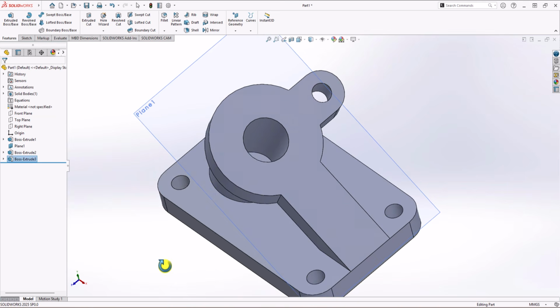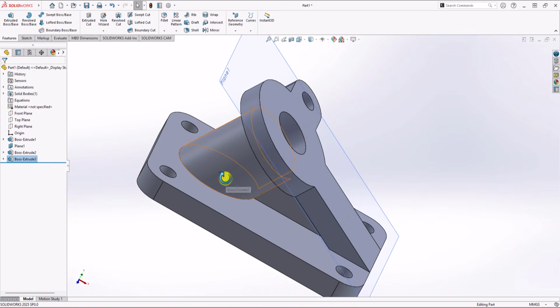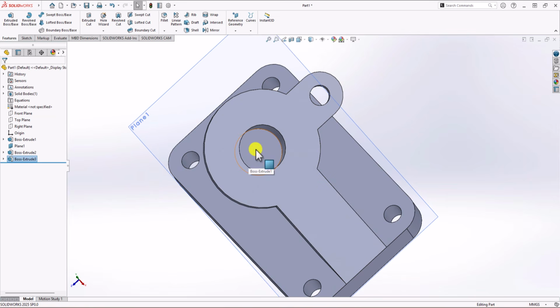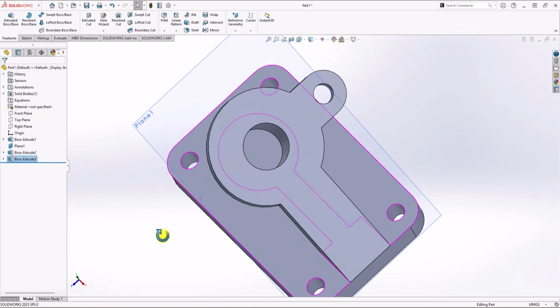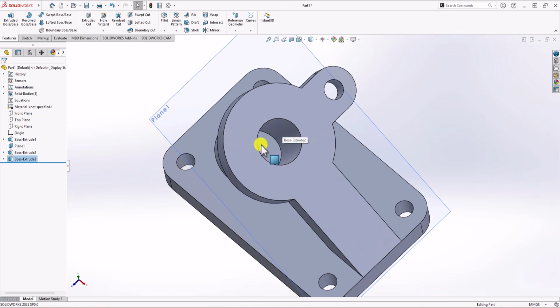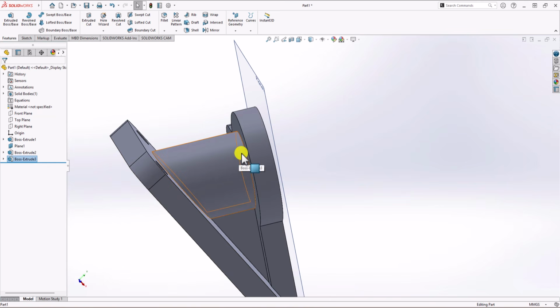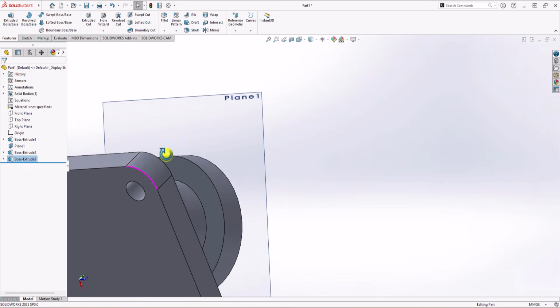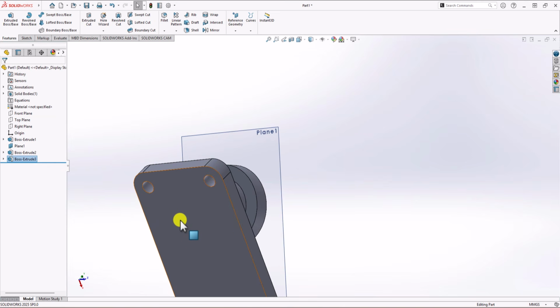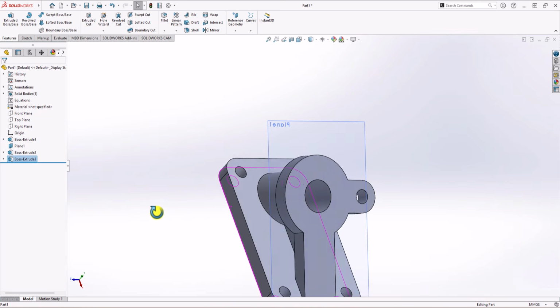The only problem is that when you make this part, you don't have a through hole. If you look at view AA, you can see that we need a through hole. We need this hole to go all the way to the back side, but here, because I extruded this part up to this surface, the hole is kind of closed. And the solution is easy. We can just make a hole here and extrude it all the way to the back side.